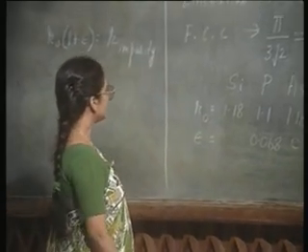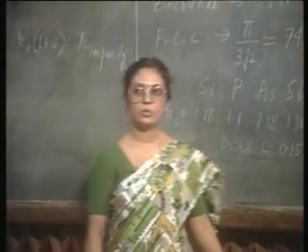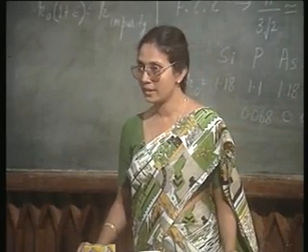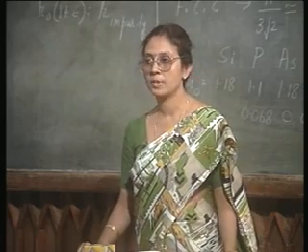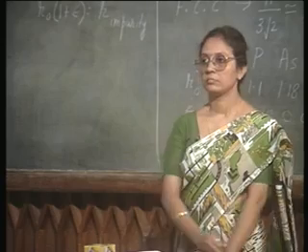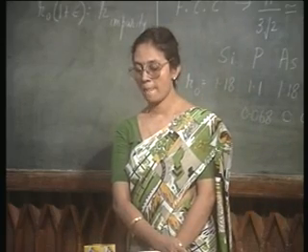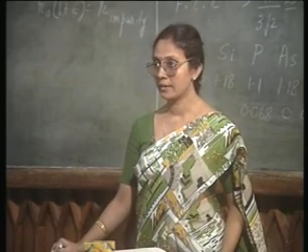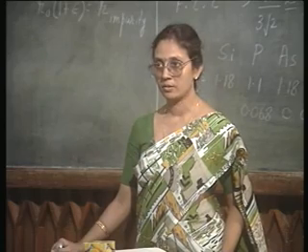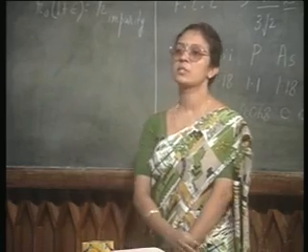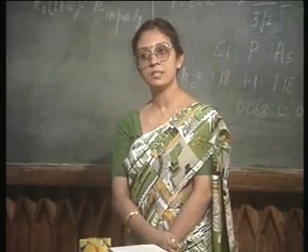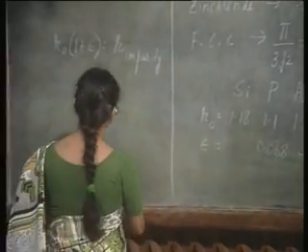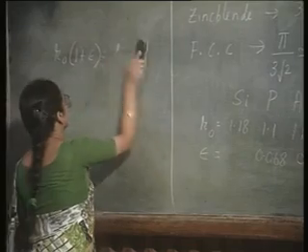So, now you know about the crystal structure of silicon, about the packing density of the particular zinc blende structure, and about the misfit factors. Next, let us concentrate on the crystal planes, that is the crystal orientation. We mentioned that for certain particular applications we prefer certain planes. Why is it so? Let us first look at some of the common crystal planes.